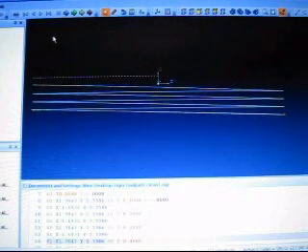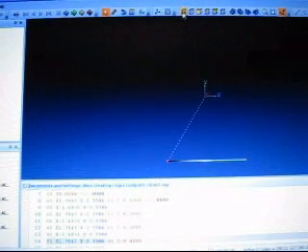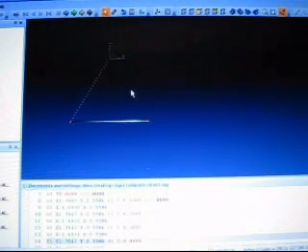but I think I'm going to just let it go at this point. I'm not really too concerned about it. Frankly, I should be able to cut 3 times the width of the tool in wood without difficulty. Okay, and I've seen machines do this at 2,000 inches per minute. Alright, we got cutting tools today that will, believe me, they'll cut.